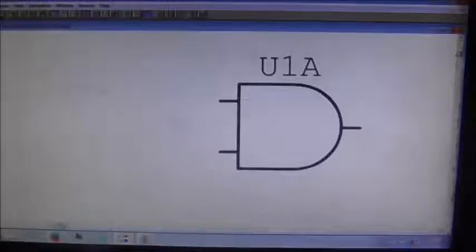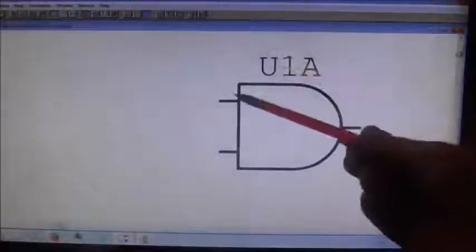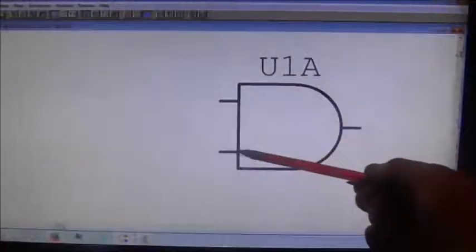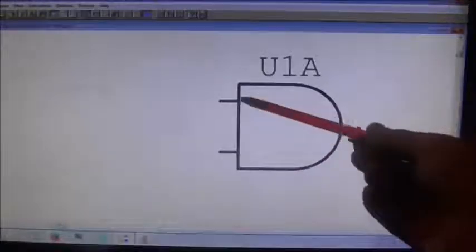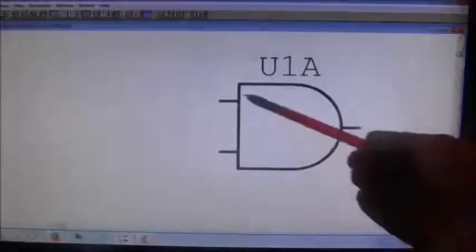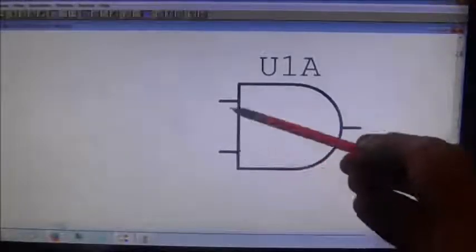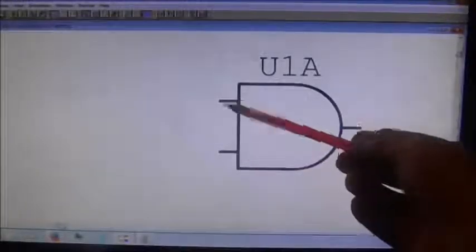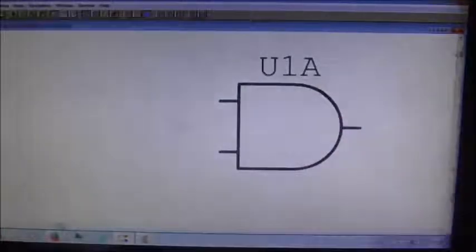Well, to conclude this film then, what we'll do is we'll look at those caveats I mentioned, and it's to do with the inputs. And if you watch the videos I made before, you'll have heard me going on about things called pull-down resistors. And the inputs of the gates have to be tied reliably to ground if you want to use them in the way we did before.